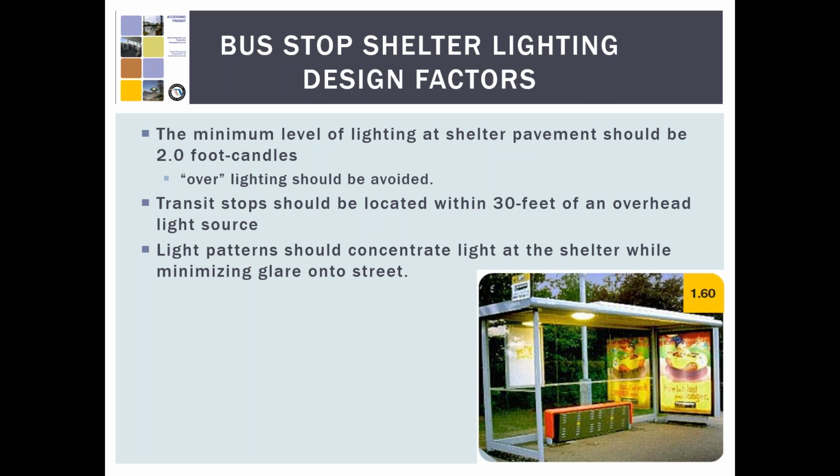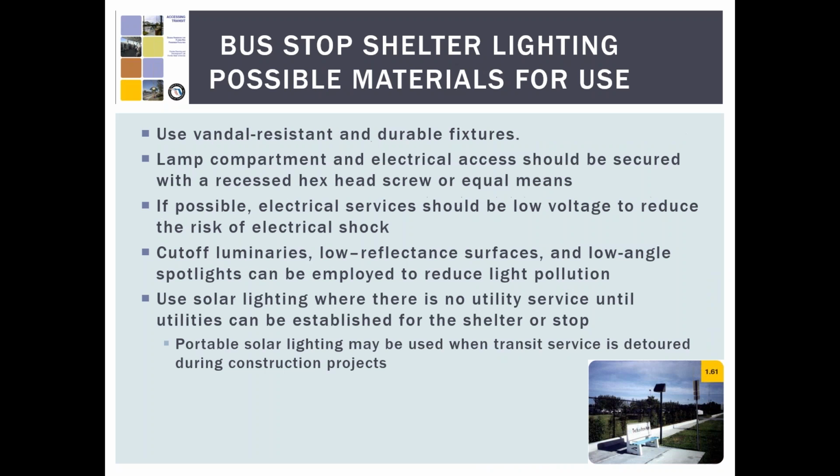For road lighting installations, light near and above the horizon should be minimized to reduce glare and visual intrusion. If pedestrian paths adjacent to the transit stops are illuminated, the height of the light fixture should be appropriately scaled, and the use of specifically designed equipment that minimizes upward spread of light near or above the horizon should be used.